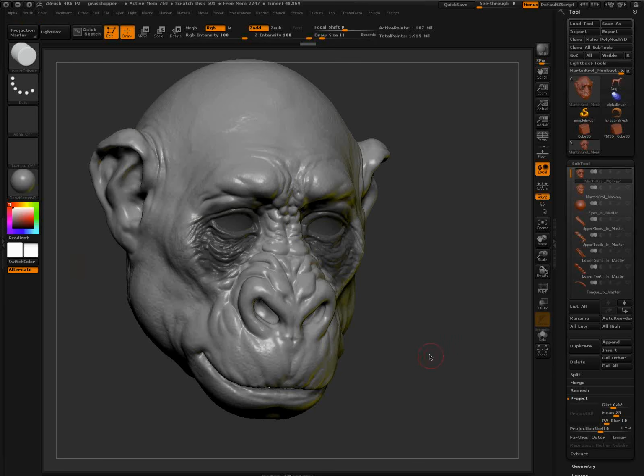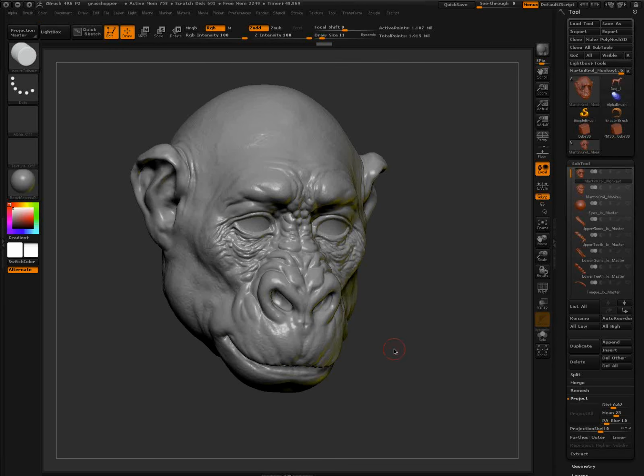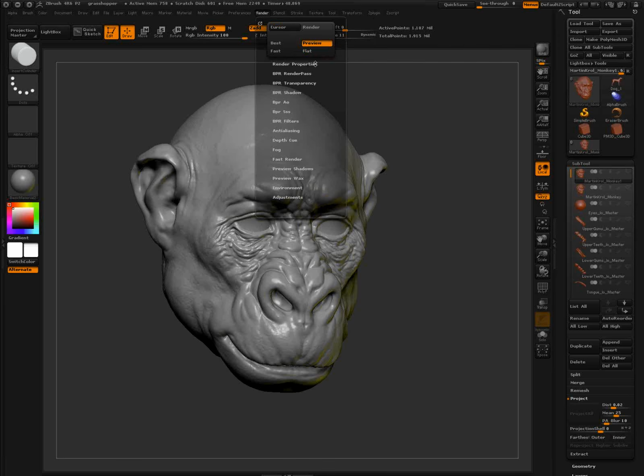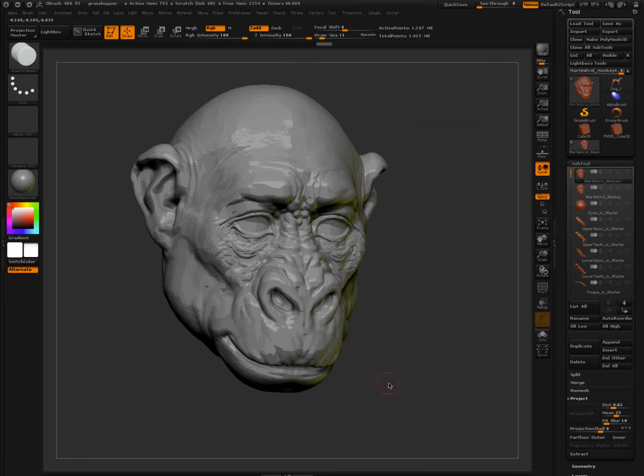Okay, and then really quick, the question about toon shading. There are four ways you can kind of do it. The first one is a 3D way, and what I mean by that is it's not like Photoshop. What Photoshop's doing is taking a 2D image, which we also have, and in essence just posterizing it. We actually have 3D, where if I turn this on, it's looking at the actual model and normals and posterizing based upon the normals. And then you can play with the roll-off from this as far as the exponent. So the number of posterize, in essence, is the number of steps that you're going to get.